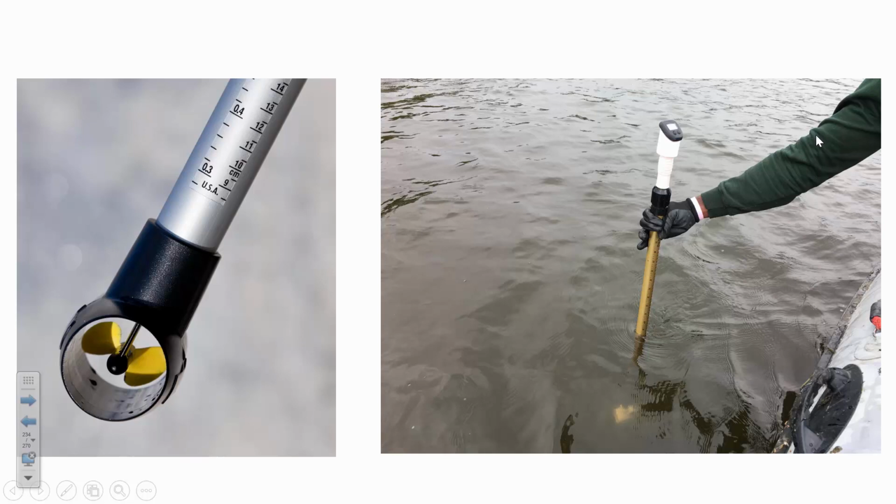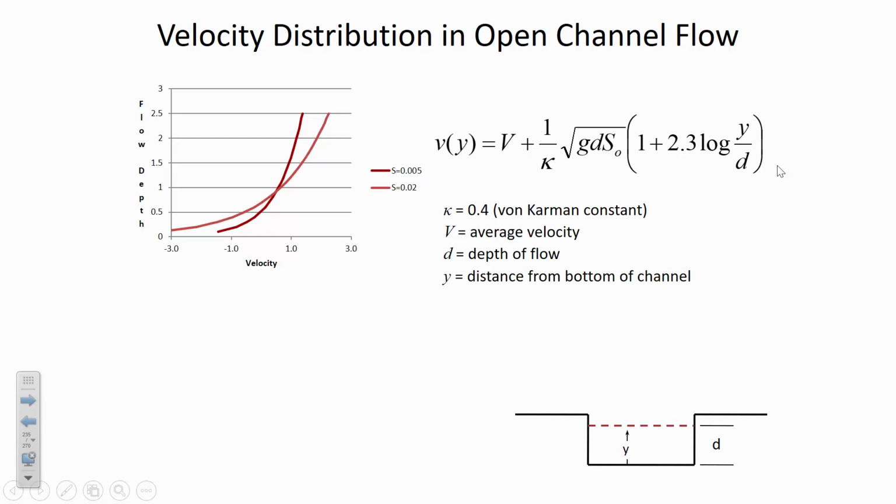If we were going to go in 1 meter segments and then measure at depths of, even if you did it at 1 meter depths, now you're talking about hundreds of velocity measurements. So that probably by the time you got to one side of the river, conditions have changed, given the amount of time it took you to do that. And so rather than always relying on direct measurement, there are ways to say what's the velocity as a function of depth,